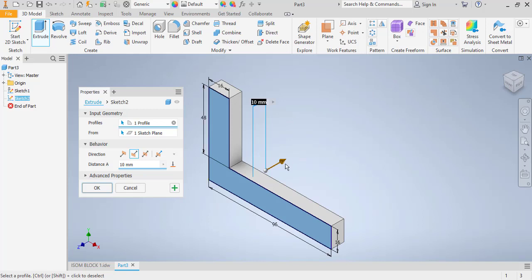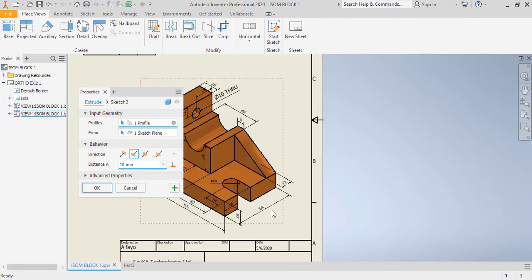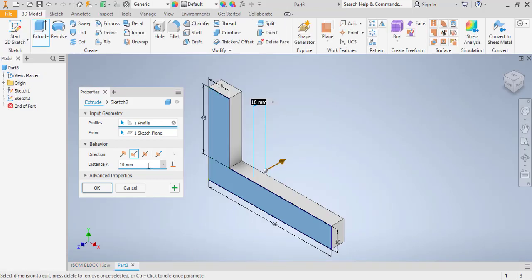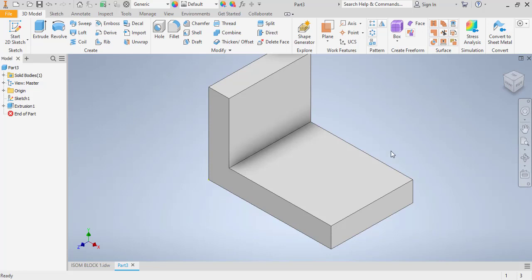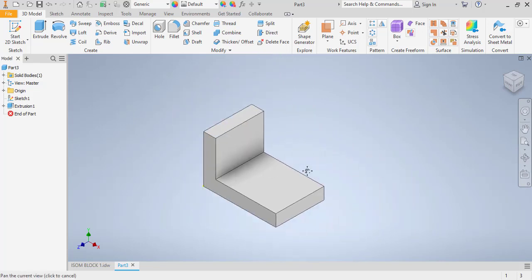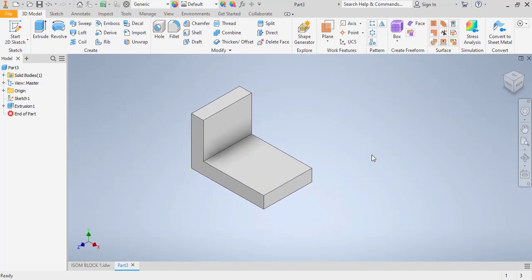But I want to position this extrusion towards the inside part, and I'll show the length. In this case, the length I'll refer to the diagram or the drawing. Here it is 64 millimeters. So I'll go back to the drawing and select the distance of extrusion, which is 64, and that's it. I've completed. I say okay. Now I can pan, zoom, and zoom extend to give me the position and the view of my choice. Now here we are.